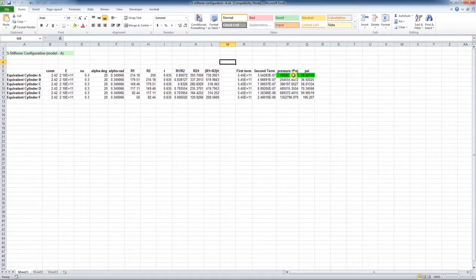Of course, the one that's the smallest is the one that's going to control, and in this case it was the one near the top of the cylinder where it is the widest section, so away from the tip of the cone. And for the 5 stiffening ring configuration, it was calculated to be about 28 psi for the critical buckling load. What is that, about 193 kilopascals. Okay, so that's a pretty good pressure. So I'll give you one of these spreadsheets, and you can see where these terms come from and play around with that if you'd like.